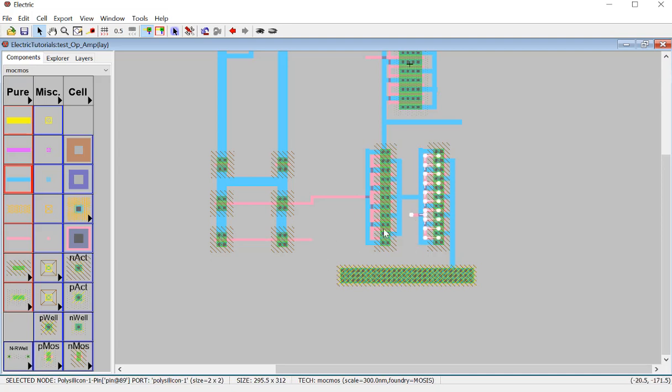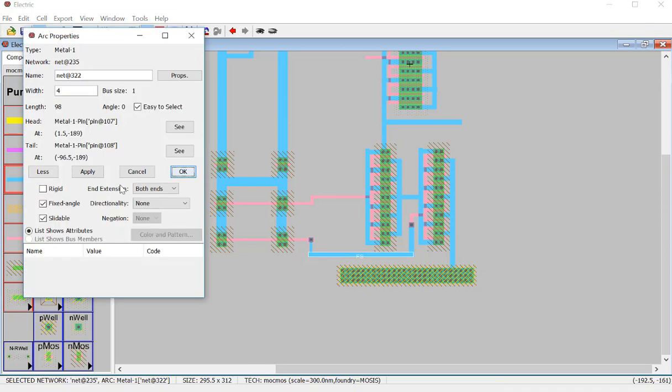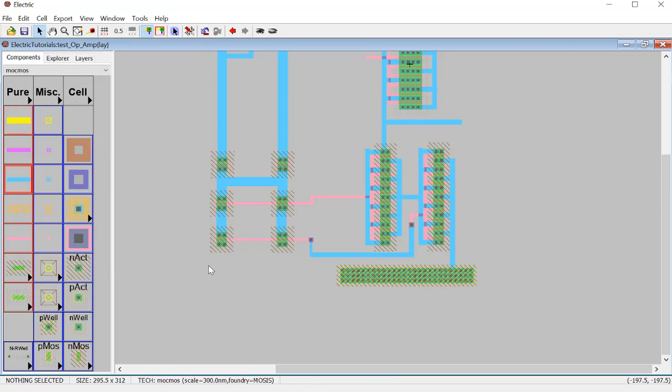And usually, I don't know, I think that's fine. Usually they don't want to make a really long polysilicon connection. So this from here to here is considered a little bit too long. So let's do this. Let's use the metal one, trying to reduce the resistance and to reach this point. Let's not extend it. So here is V bias 3 and V bias 4.